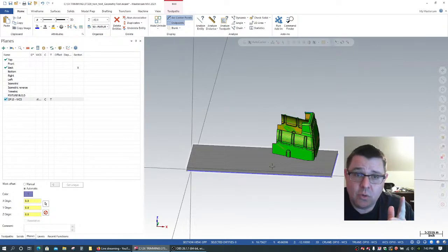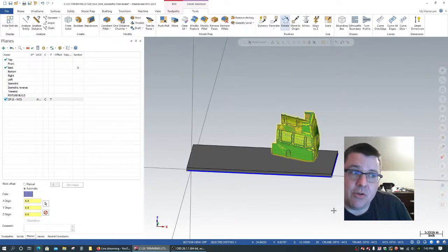So you've got a known tool length. And then you just use some drill tool points with a stop at a point, and you can measure how far the model actually is in 3D space from where you think it's at in 3D space. And the point is, if this geometry is not right, move it.